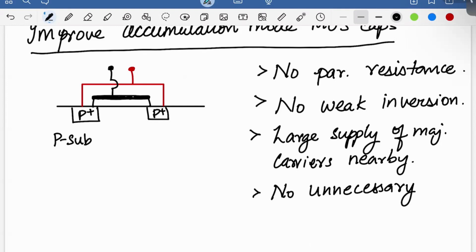And that always leaves some parasitics in, because you have something that you're not using, right? So in this case, you don't have that. You eliminated unnecessary contacts and unnecessary regions, so you have a better, cleaner parasitic model, basically, right? So no unnecessary parasitics. That's actually a big advantage.